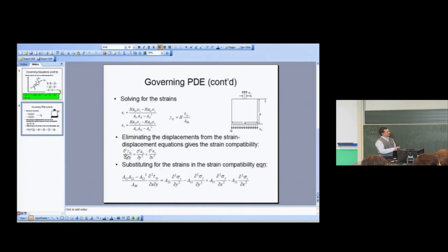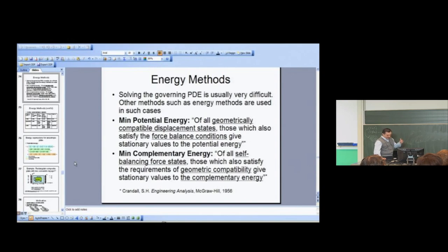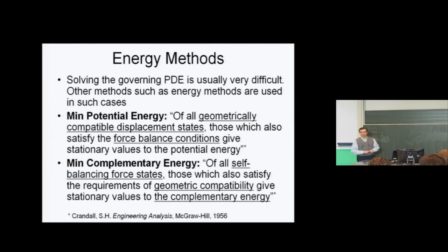Remember, we said last time that if you eliminate the displacements, you can come up with a relationship that combines only the strains. So that is the equivalent of the strain displacement equations. So you can satisfy that exactly, which means you are making a displacement-based solution, which most finite element models actually do. And you can satisfy your geometric boundary conditions. That means any boundary conditions on displacements. You don't do anything about boundary conditions on the forces.